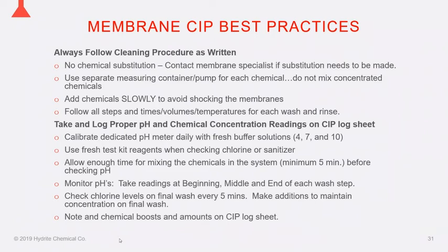But if there's a lot of soil in the solution, that chlorine is going to fall off so fast, it doesn't make sense to maintain it. It's kind of a garbage wash, get it in, get it out. The final wash is where, if you do have a final chlorinated alkaline wash on your UF system or MF system, you want to make sure you maintain that level of chlorine.